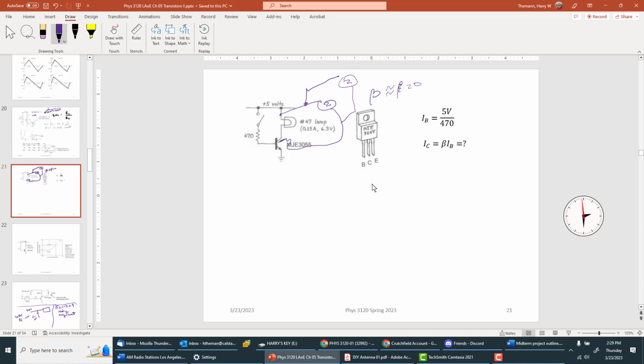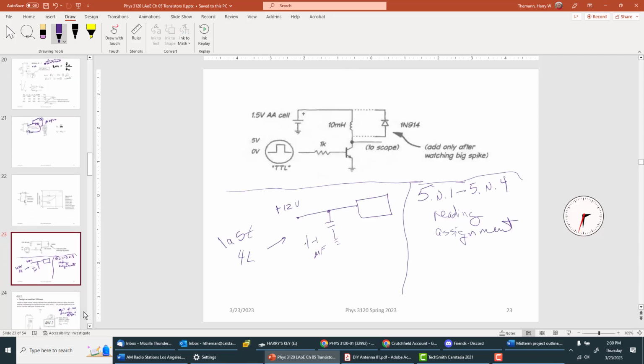These metal things with fins on them dissipate the heat. And if you were to open up your power breadboard, you'd see a power transistor like that. They're specifically made, and I think it has to do with the emitter, base, collector. One of those three is attached to that metal tab on certain of these transistors. I don't know why electrically it's done, but physically it's done to dissipate heat, so it doesn't break when it gets hot.